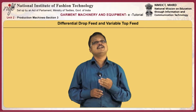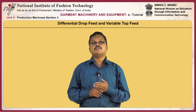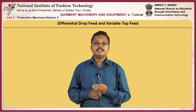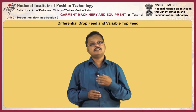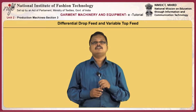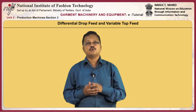Differential draft feed and variable top feed. This 4-motion tandem feed has an adjustable top feed system that is used by almost every top feed overlock machine. Description: it features 3 separate feed mechanisms, one above the pressure foot and 2 below, each moving at the same or different rate of speed to produce a flat seam. The feed can be adjusted to stretch or gather the material. The application of this feed system is to ensure an even finish when joining 3 plies of fabric, and it is used for piping operations on sportswear, tracksuits, pyjamas, lightweight jackets, cushions and upholstery.